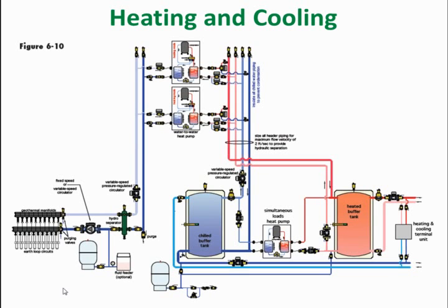Because what happens when you cool water is the volume contracts, just like when you heat water, it expands. So you really need a little bit of reservoir, a little bit of capacity there to handle the change in temperature in this fluid, because it does change between heating and cooling and different load conditions. So we're showing it with an expansion tank, and also a little fill system here.